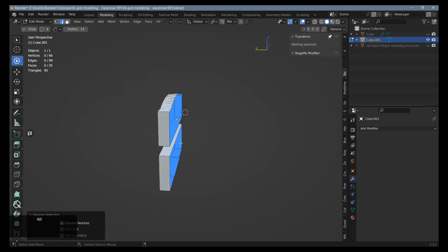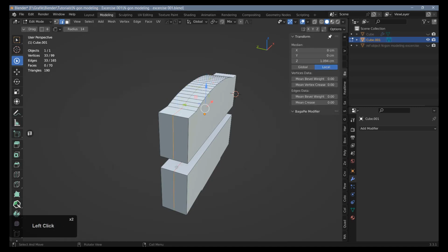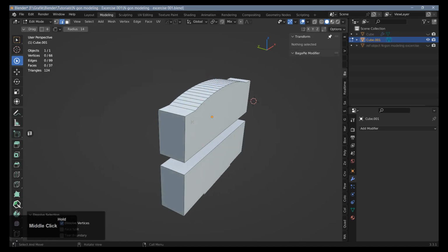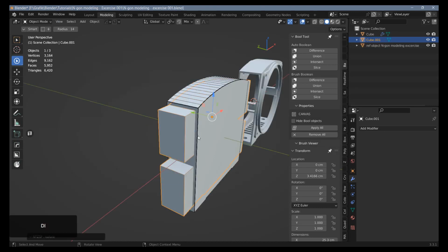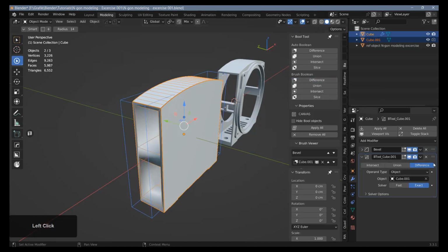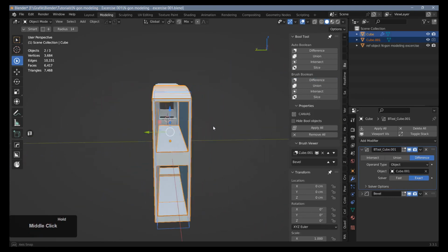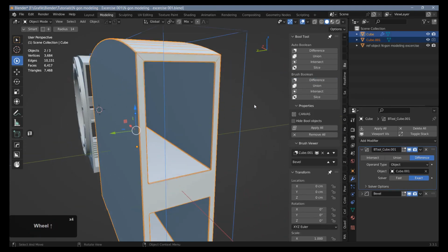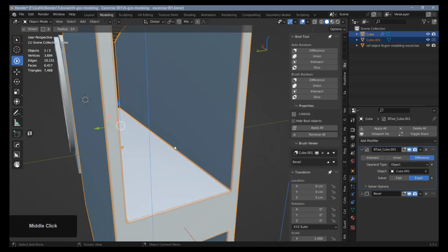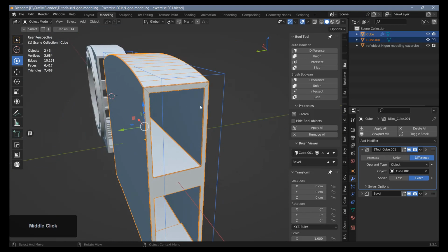Let's go ahead and mirror this over. I'm going to use Mesh Machine to do that, and then I can loop select the edges here, Control X to dissolve them. Let's go back to object mode and hide everything. Select our model here, and let's do another brush Boolean difference. Let's move the cutter above the bevel. And that's looking good. Everything's nice and clean because we cleaned up the cutter. We're not getting any unnecessary edges here that we need to clean up on our model. And in my case, Blender has also created nice connections.